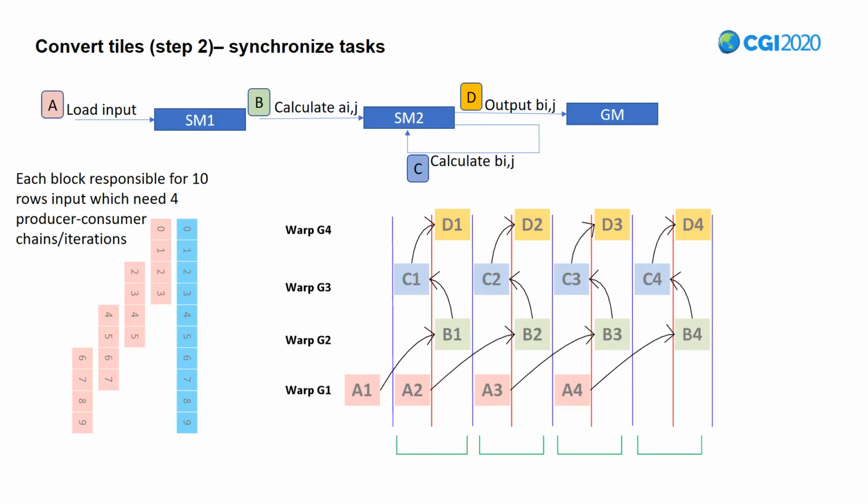Warp specialization allows subsets of threads within a block to have their behavior tuned for a particular purpose, which enables more efficient consumption of constrained resources. To prevent the warp's execution from being blocked by too many synchronization instructions, grouped producer-consumer chains using named barriers in PTX are designed to reduce synchronization and achieve data safety.